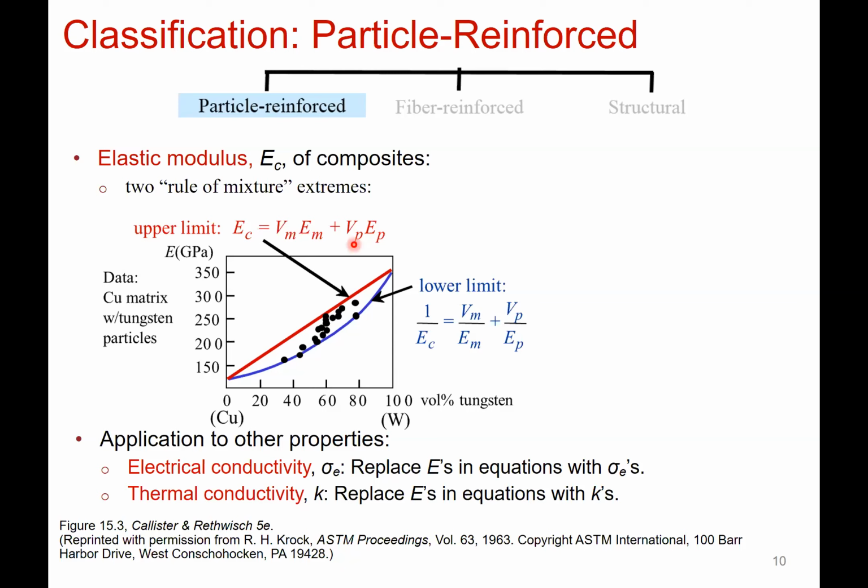the volume fraction of the particles that you've added in, right? So if you added in 10% by volume, 30% by volume, that's 0.3 here. That's the volume fraction or the volume percent. The lower limit, which can be derived from the iso-stress conditions we'll talk about, is going to be the lower bound of your range.